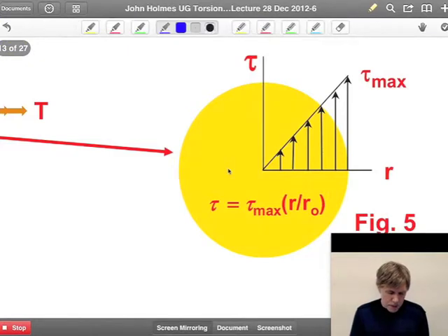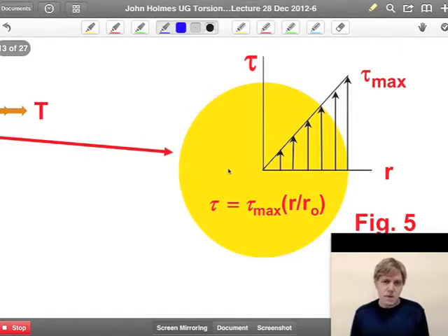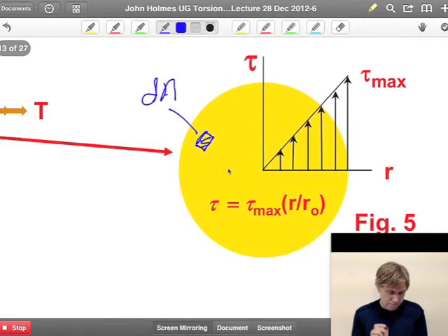Now, just as we have internal stresses in a beam, either bending stresses or shear stresses under bending loading, we also have these internal shear stresses that develop in the material elements during torsion. So suppose that we take a small element of material here, and let's give it an area dA, and that acts at a radius, let's call it r, from the center line of the shaft.